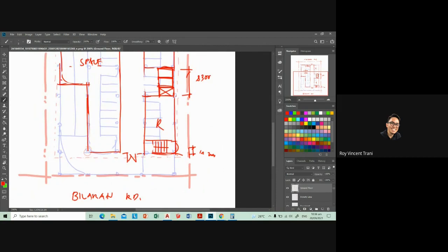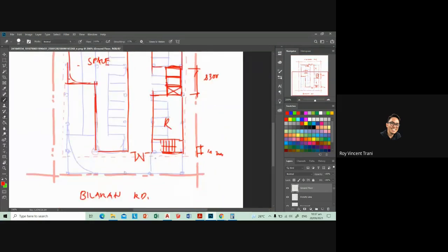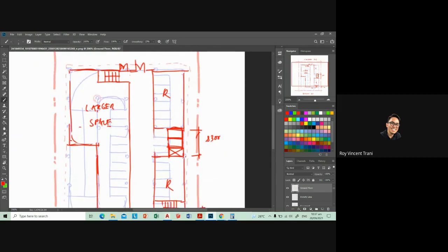Okay. So the fire exit for all your works need to exit to the exterior of the building. Then maybe you can hide it with some shrubbery on the outside, like some design on the doors. But they should be sort of like this. We don't need to worry about access to the fire exits from your ground floor because the fire exits are really for the upper floor.